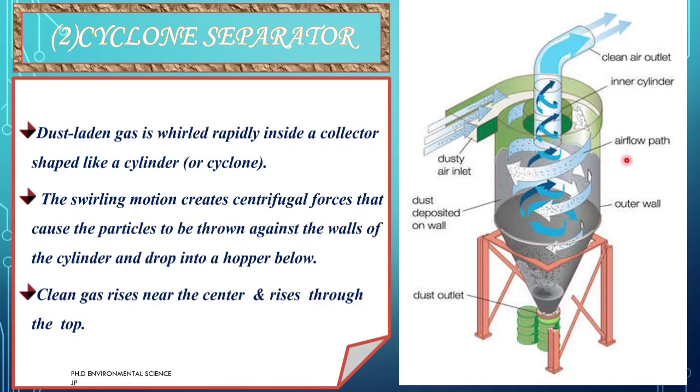Second is cyclone separator. It is also known as cyclone collector, and it is a device which is used to remove particulates from an air, gas or liquid stream without the use of filters, through vortex separation. When the dust-laden gas enters the cyclone, it is forced into a swirling motion, creating centrifugal forces that separate particles from the gas stream. Now, first, let's understand its components and functioning.